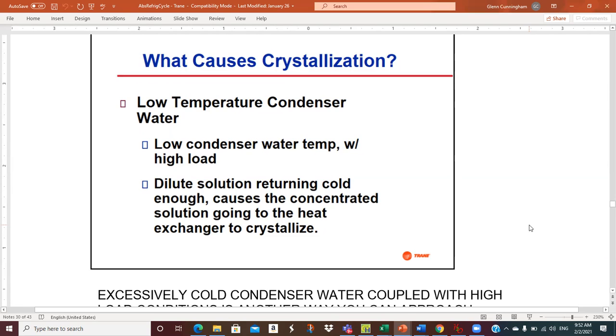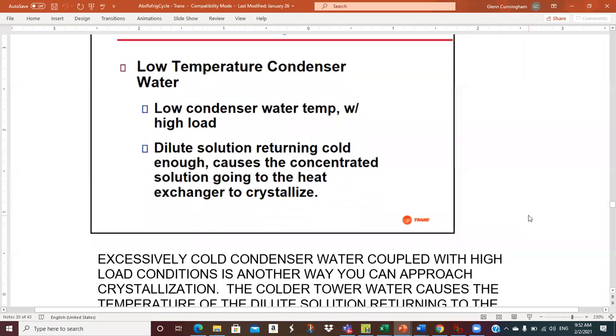Now, it's interesting, on a centrifugal machine, you often want to do that to reduce the energy on the chiller. That's an area of discussion amongst chiller plant operators: how hard should you run your tower fans, because that's more cooling tower energy, in order to reduce chiller energy. The chiller is the biggest motor, but you have to go through an exercise, and it depends on climate and some other things. So anyway, low condenser water.